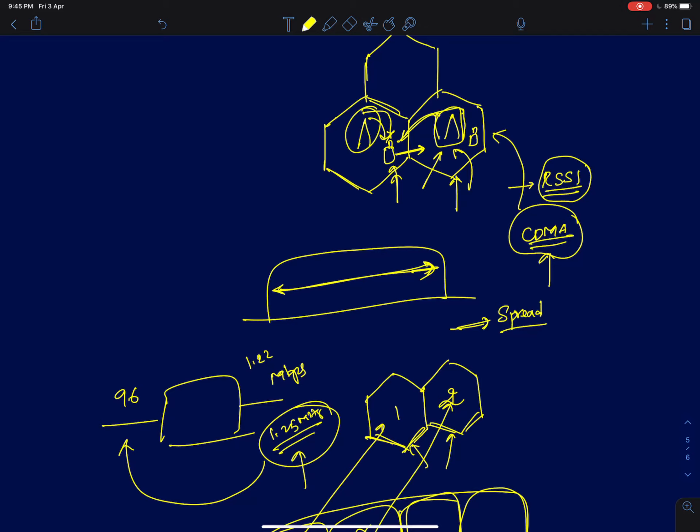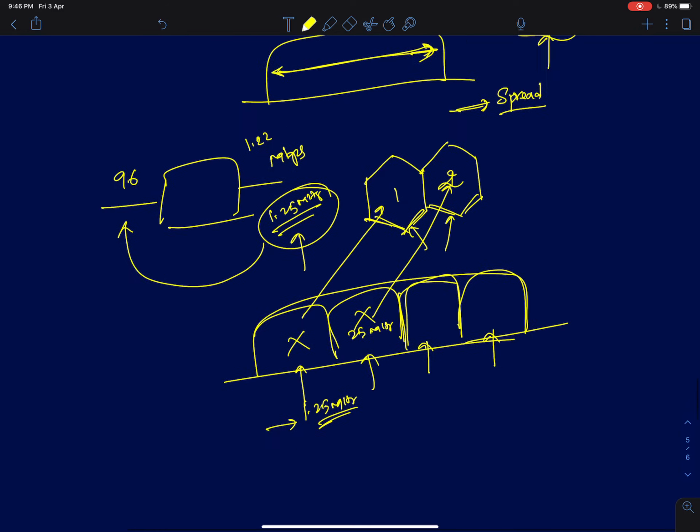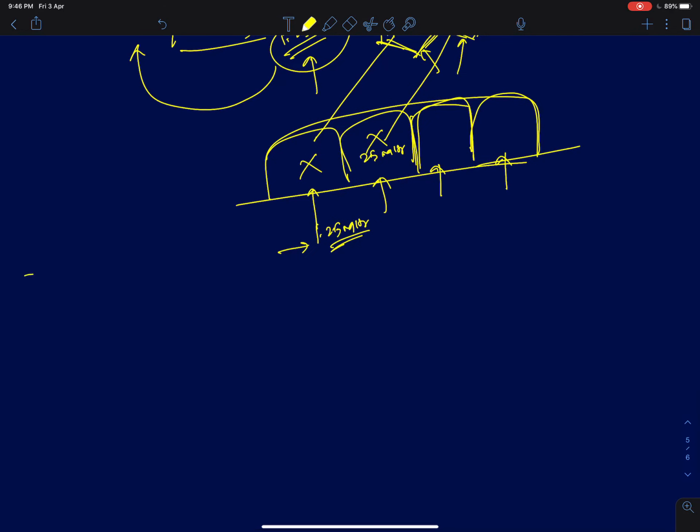It's receiving extra signal power, so wherever the signal, especially at the cell edge, is when its signal power is going to go low. But now since two base stations are transmitting, its signal power will be good enough to give you good communications. Okay, so this is the soft handoff advantage of CDMA, and which was one of the selling points when it was competed against TDMA, the GSM second generation GSM phones. So this is it about the basics of cellular communications.